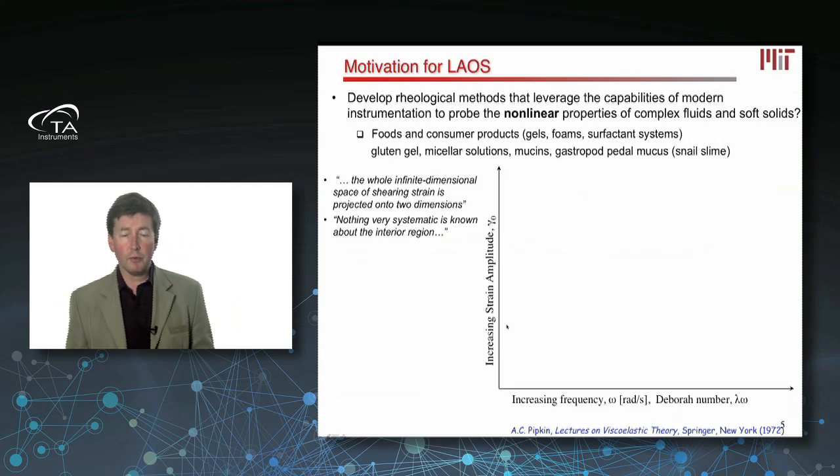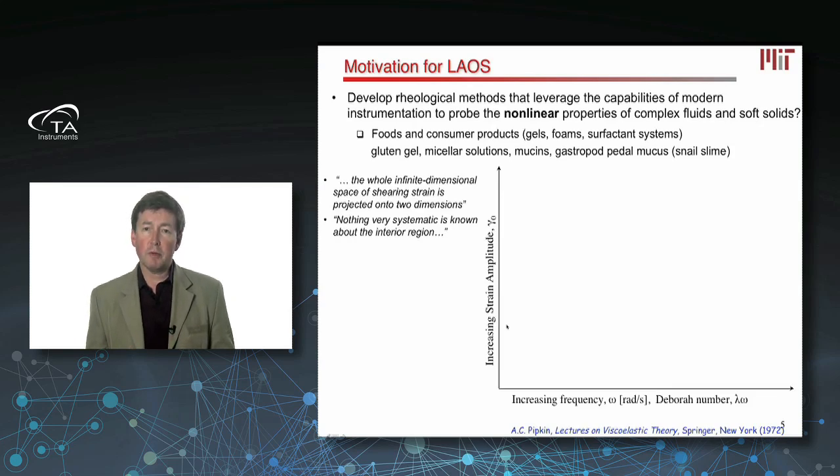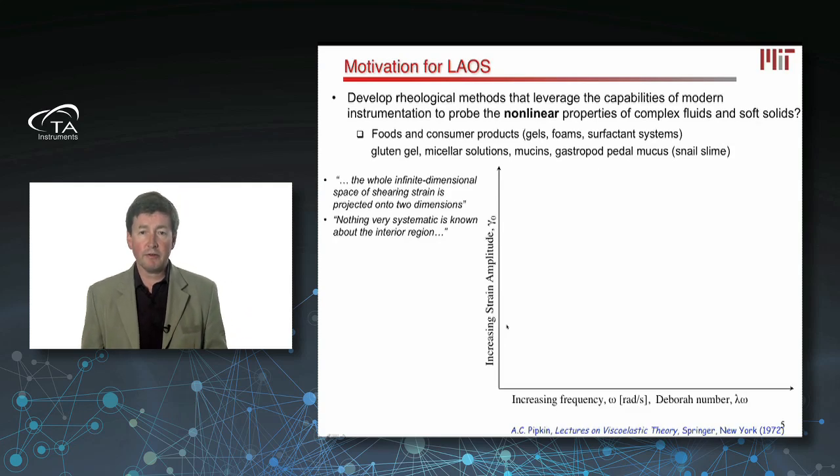What we really want is a rheological test that really exploits the capabilities of a modern rheometer. We all know how to do small amplitude oscillation. Everybody may be familiar with doing steady shearing deformations, but there's a wide range of other kinds of tests that a modern rheometer can do. Typically, if you have a complicated material, then you really want to push the material into the nonlinear range and try to understand the response not just in the linear viscoelastic range, but also the nonlinear range.